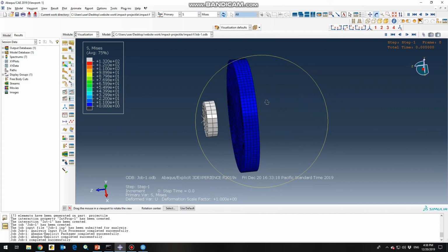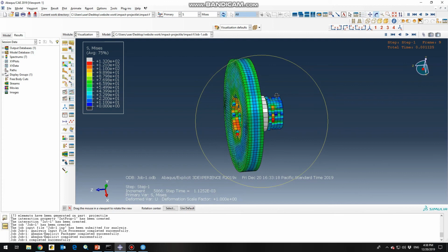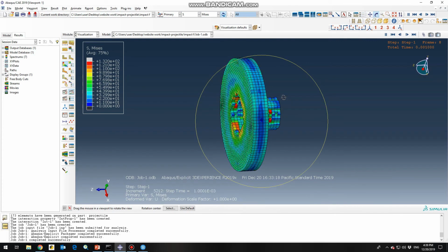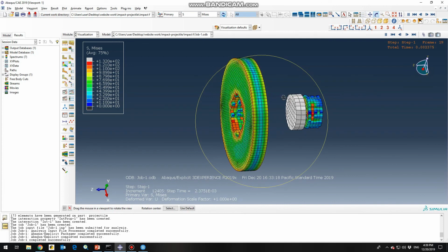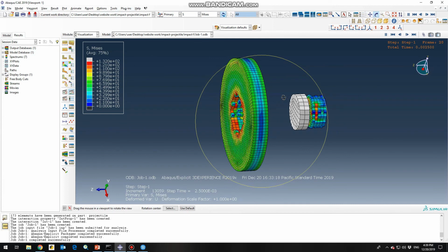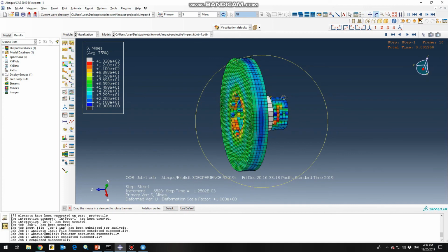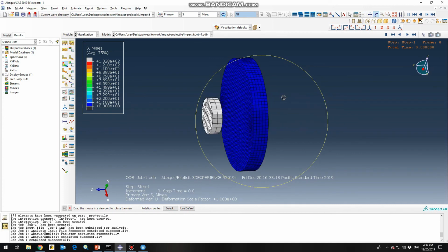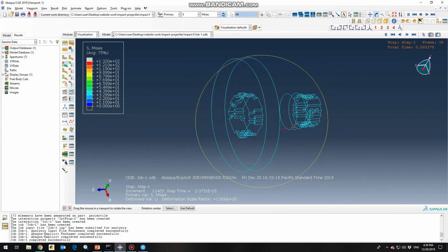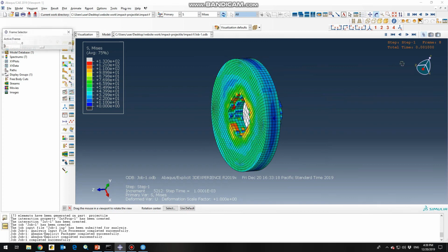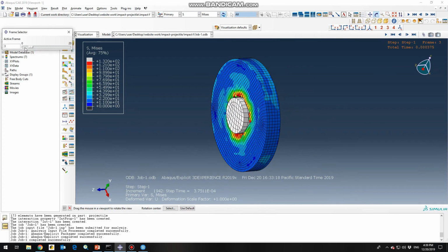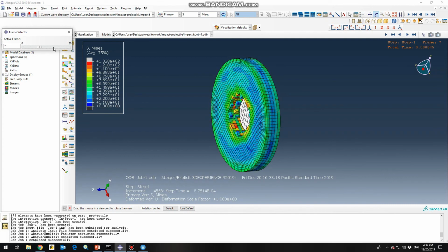Because of the shear failure we've defined, and considering the fact that we chose element deletion for the circular disc in the mesh section, after the projectile hits the plate, the elements will be deleted. Also, you can click this and see the validation section by section.